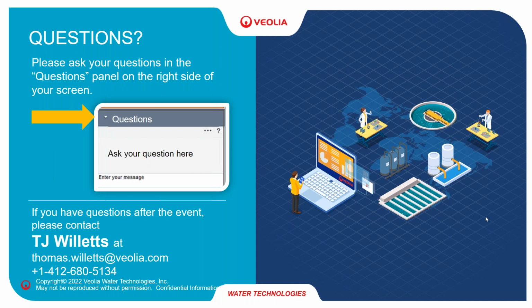Question for you, Matt: could this system be used to recycle wastewater from a CNC machining company that uses coolant emulsion and also water from parts cleaning with soapy water? That's a pretty open-ended question. We try to segregate the waste streams sometimes, depending on how we can do it. Certainly, for anything with a heavy foaming tendency, we can feed anti-foam to the system to be able to run it and recover it. Typically, we're able to treat pretty much anything as long as it has some consistency to it. We certainly want to collect it in an EQ tank and then feed it from there.